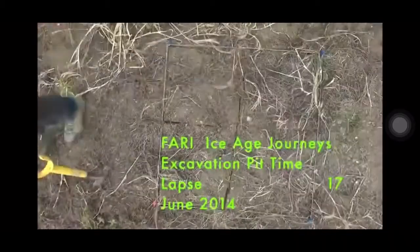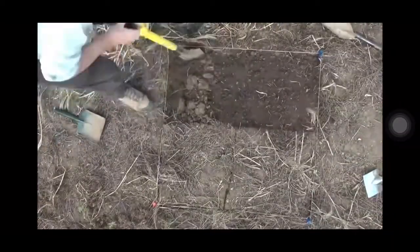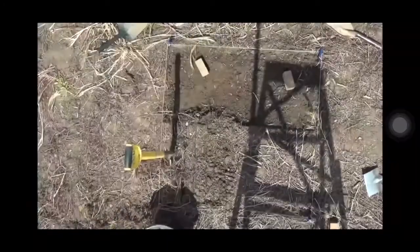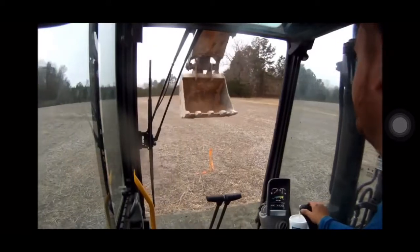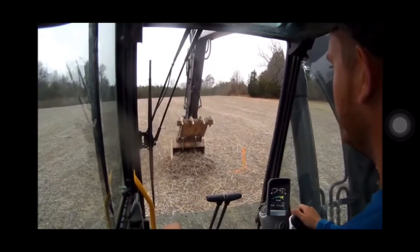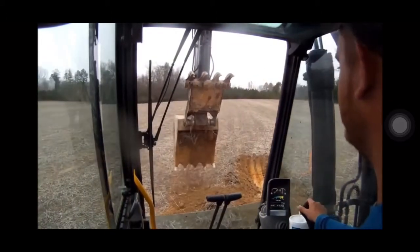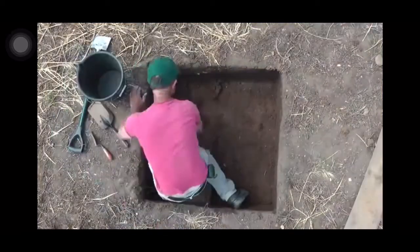Test pits are carried out in order to recover large bulk samples of soil or if detailed visual examination of the strata is required. The process: samples are taken by cutting soil with caution and being careful. Soil can be dug by hand or using a backhoe excavator, generally up to 3.5 meters deep. If the test hole is greater than 1.2 meters and is intended for human access, then the hole should be made safe from possible structural collapse. Samples taken are stored in airtight containers.